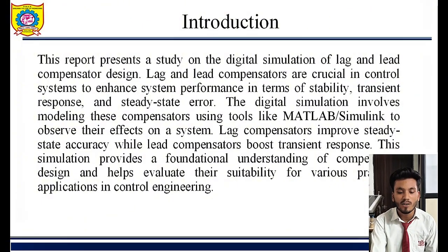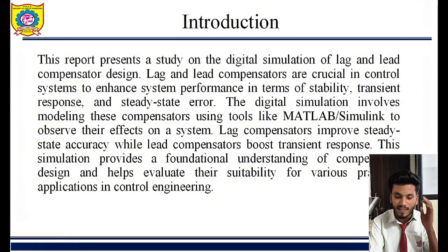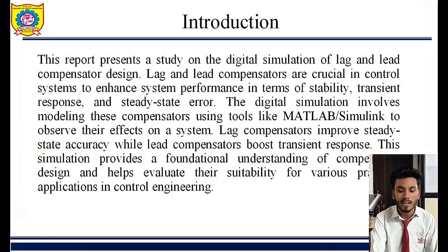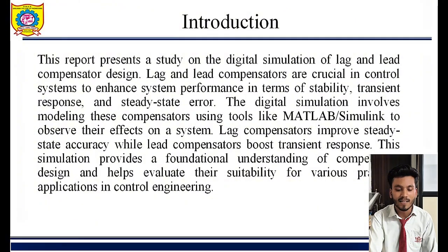Digital simulation involves modeling the compensators using MATLAB simulations and observing the effects on the system. The lag compensator improves steady state accuracy and the lead compensator boosts the transient response. This simulation provides a fundamental understanding, and compensator design helps improve the stability of various practical applications of control systems.